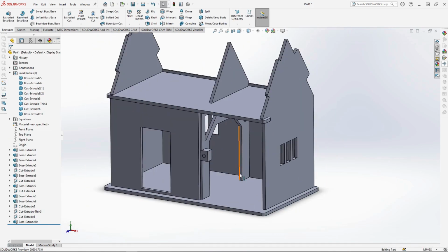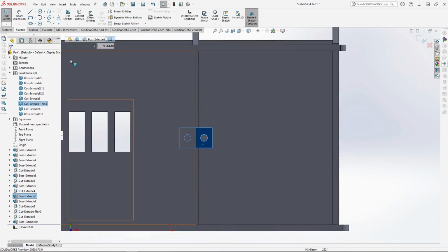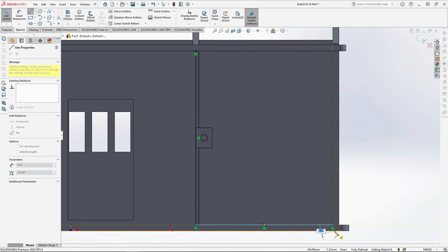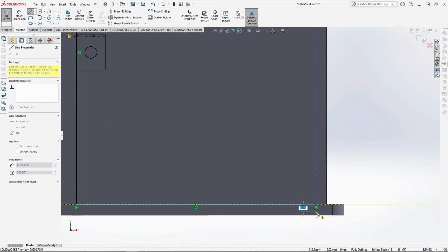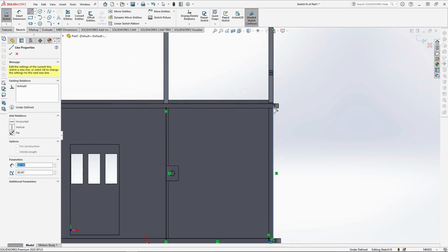For the other door, start another sketch again onto the magnet block and sketch from the middle again down the door panel, along the base edge by 204mm up to here, down by 4 again to add the pivot, go across by 9mm and back up by 267mm level with the other door. Add the top pivot of the door and close the profile.